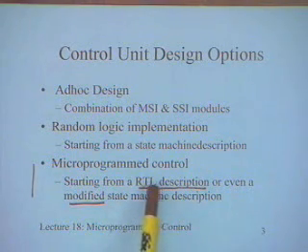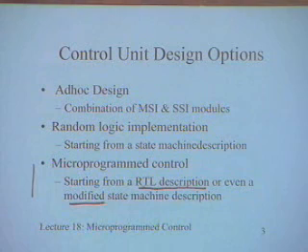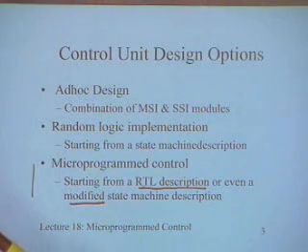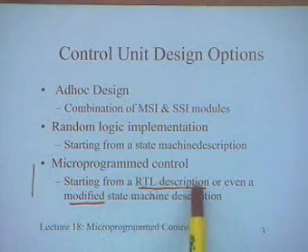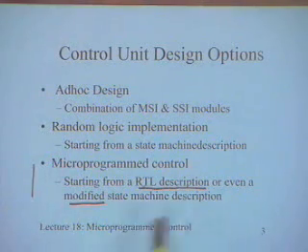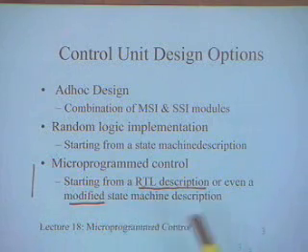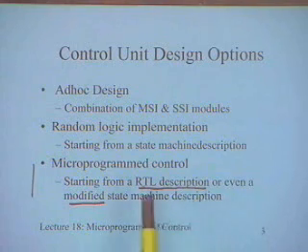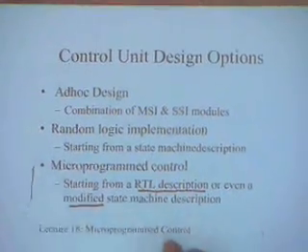So you can specifically say that if I want to perform a certain transformation, how can I perform that transformation? What multiplexers have to be selected? What input has to be given to the ALU to perform an addition operation? Those things are already known, and then you generate using a microprogrammed control. Of course, this RTL description will get clearer as we proceed beyond this module, when you go to the next module, but for the present we will concentrate on how you can relate to what we have done with the state machine, that is, how we will do it for the microprogrammed control.